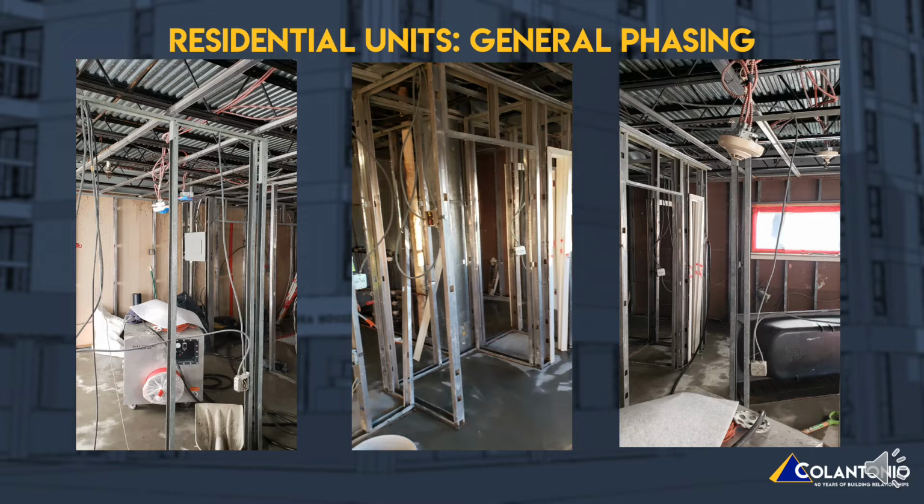Before continuing with the phasing, one point to make here is that as part of the base bid, all gypboard will be removed from existing walls within the units as seen in these pictures. Units will be completely exposed after completion of the demo and abatement. Subcontractors should expect free and clear access within interior walls of the units to perform their work. Additionally, any hanger installation or other work requiring drilling into ceilings should not need to be done in containment.